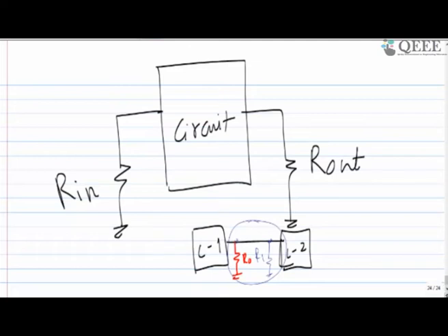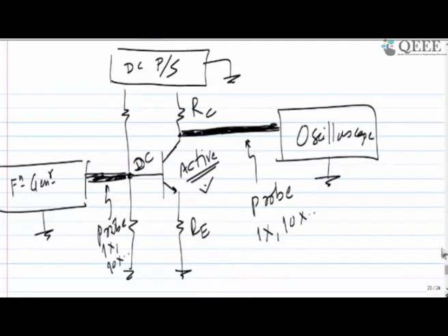So all the instruments, the function generator or oscilloscope, will have some input resistance and output resistance. I am not taking the output from here, but there is one more resistance. Sorry, I should say R out. So every circuit will contribute R in, R out, R in, R out, and they are the problem for me.